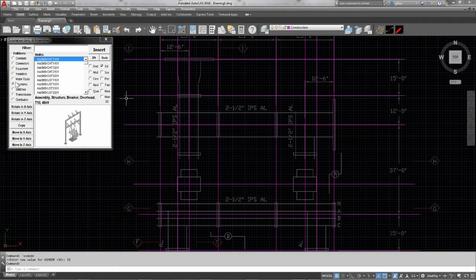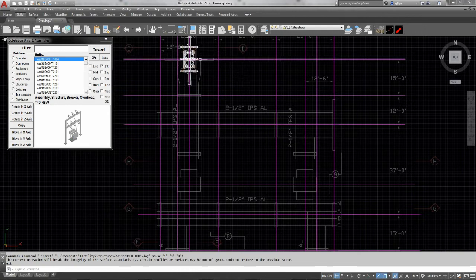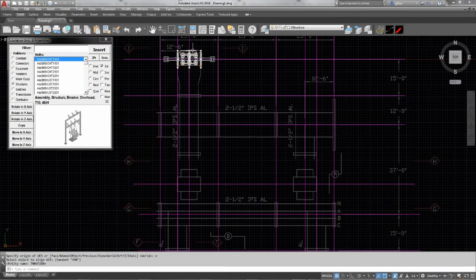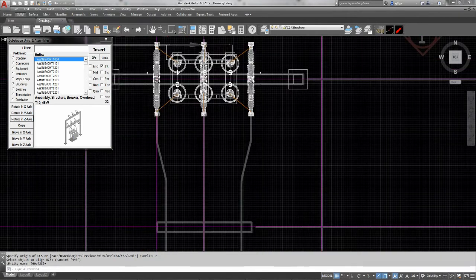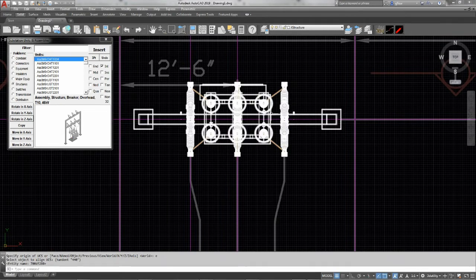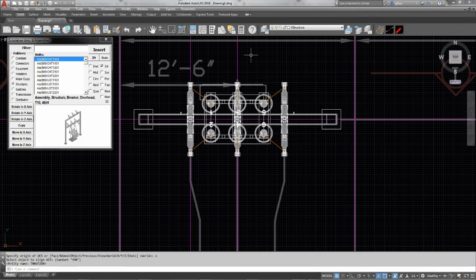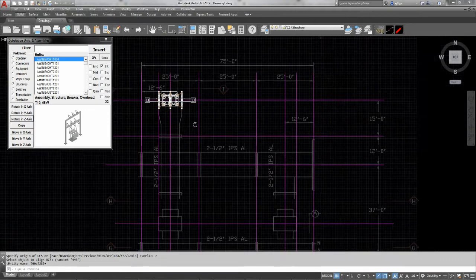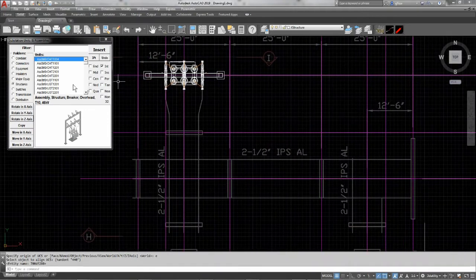So to insert that, we've got intersection selected here. We just click insert, and we snap to our intersection on our construction lines, and here we need to rotate that 90 degrees, and we'll notice here if we zoom in that it's rotated such that the 1, 3, and 5 bushings are both on the line side, which is what we typically want on our dead end structure.